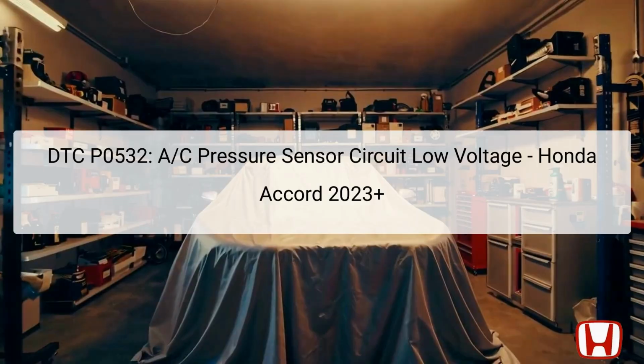The Diagnostic Trouble Code, DTC P0532, indicates an anomaly in the AC pressure sensor circuit, specifically that the output voltage of the AC pressure sensor is lower than specified limits. This component plays a crucial role in monitoring the refrigerant pressure within the air conditioning system, sending a corresponding voltage signal to the powertrain control module, PCM. When the PCM identifies that this voltage is below 0.24 volts, it registers a fault, leading to the triggering of this